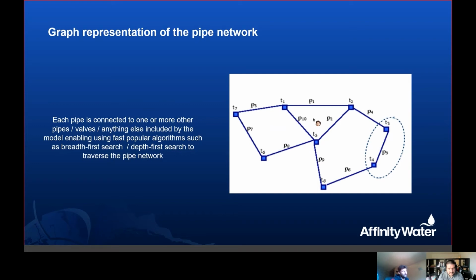So as a next step, here we append the geographical context to each node, to each asset. So if we have a logger, if we have a pipe, then they're in a certain type of soil, they have a certain type of altitude. So some of the data that we append to each node as a context includes drift geology, ground moving, shrinks and swells, corrosivity, soil classification, solid geology, and we use digital terrain model image to get the altitude.